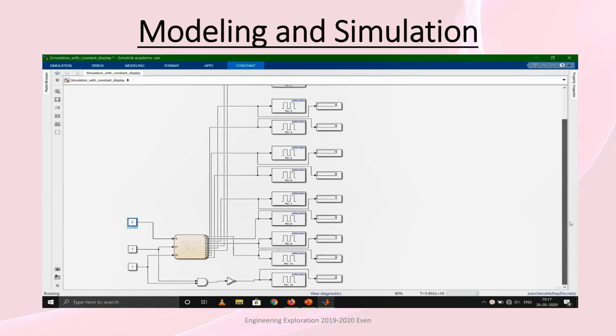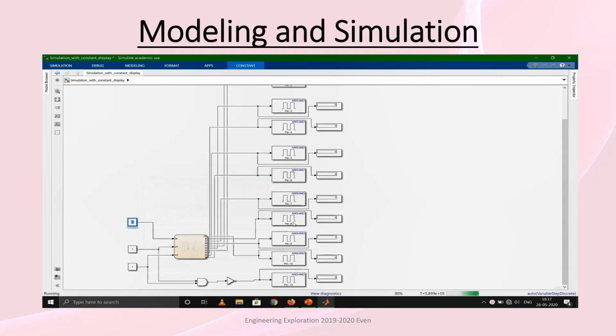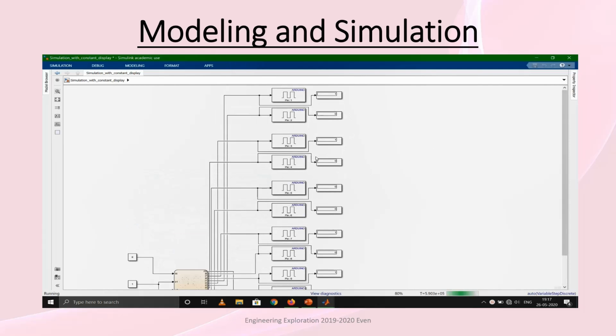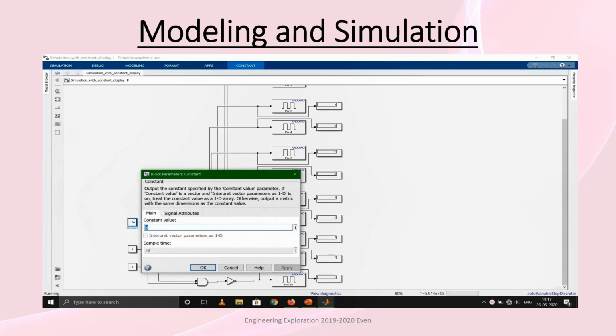Suppose we want to switch on the water spray as well. So we would give the command 8, that is for water spray. Given the command as 8, let us see what happens. Now when we give the command 8, you can see pin number 3 and pin number 4 have value 1 and 0. So the bot is going in forward direction as well as both mop and water spray are switched on.